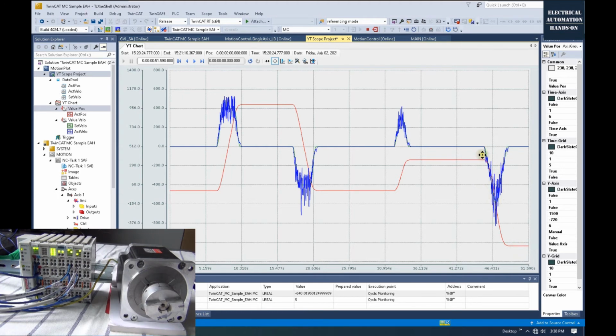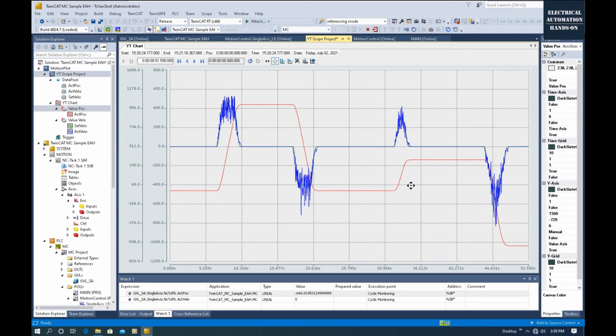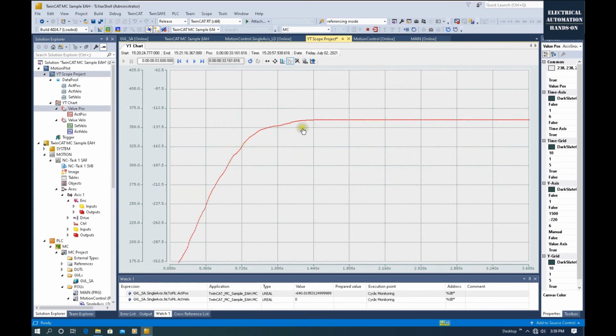And the blue curve records which speed it had at that time. For this third motion, the speed was slow. The acceleration and deceleration can give us a sense, for example, of the last motion, where I set the acceleration high. I remember that's 600. So this curve can help us watch the actual position and the speed setting, and even some optimization issues. For example, now we can see every stop, this curve looks smooth.